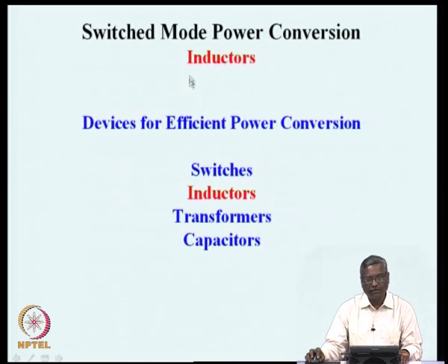And we saw the concepts of reluctance, flux linkage, the definition of the inductance as flux linkage per ampere and so on. And we saw the practical limits such as saturation limits, thermal limits and so on, and how to put all these things together in the way of designing an inductor, and we saw a sample inductor design. And we had also seen the nonlinearities, which are the core reluctance in comparison with the gap reluctance, the fringing effect, how to take care of these effects so that your design will be close to what you want. We have seen how the inductors are measured and different ways of measuring the inductors and so on.